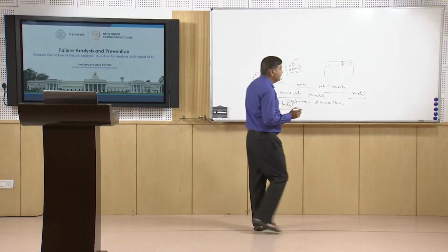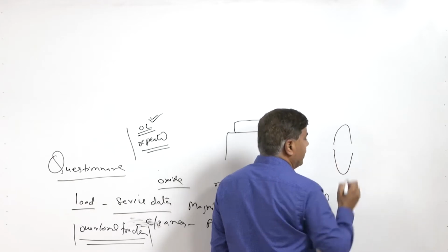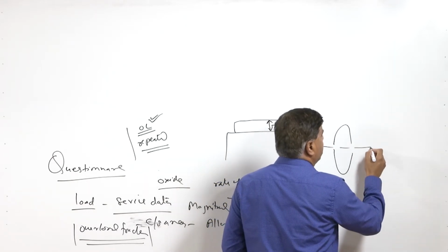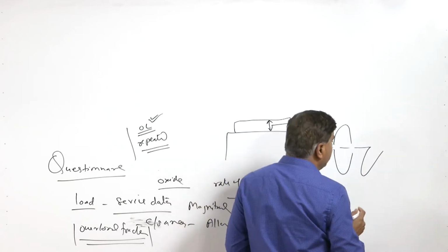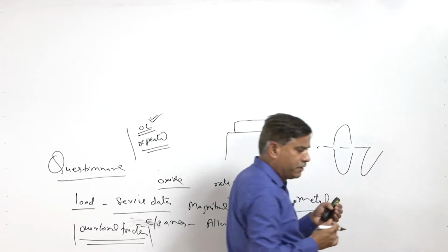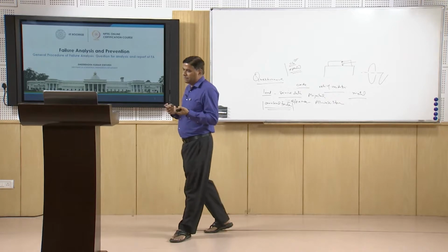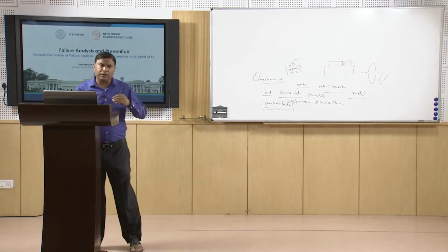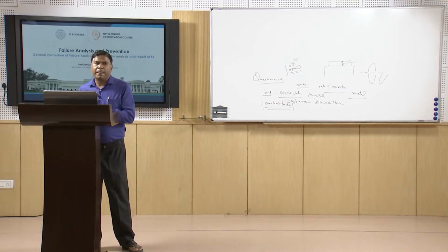For example, in case of tensile load, dimples grow perpendicular to the fracture surface, while in case of shear loading they are inclined, and in case of bending the inclination is of a different type. The shear fracture surfaces will have the orientation of the dimples in different ways on both sides, while in case of bending it is also different.